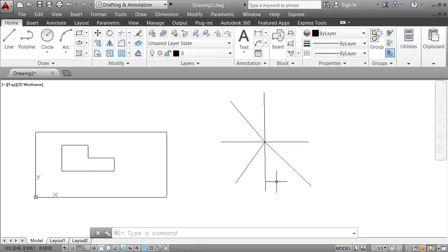All right. Same analysis, do it in this quadrant to draw this line. You say 270, if the angle is 30, plus 30 is 300. If the angle is 45, you say 270 plus 45, 315. If the angle is 60, you say 270 plus 60, 330. When you do this calculation, you will have no problem to draw the line, right?